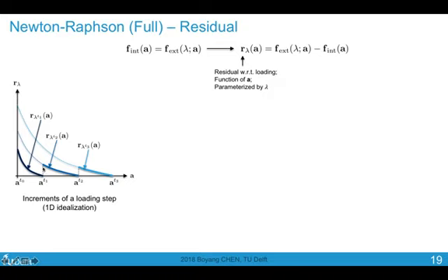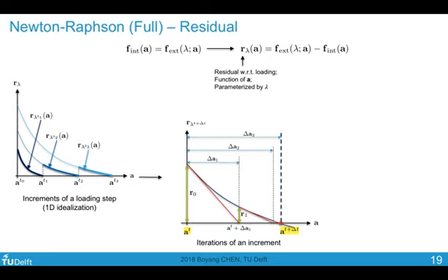And then we increase the load, we suddenly have a nonlinear, non-zero residue, and then through iteration, we find our solution for after the second increment. And then this repeats until we reach our final load level. For each of these increments, we can perform Newton-Raphson.